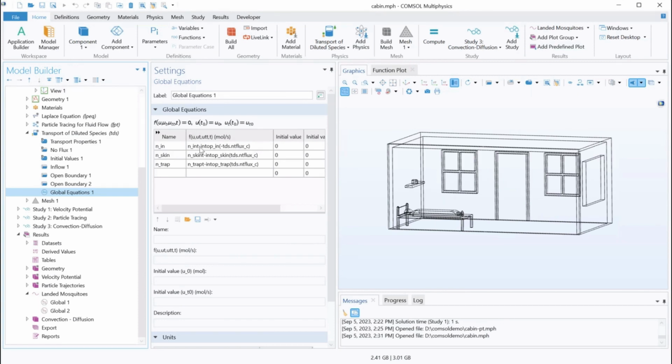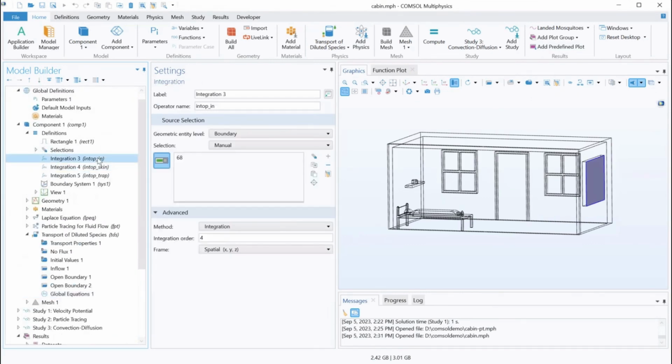So what's happening here is n in t is the time derivative. So this is a built-in expression. This means the time derivative of the expression we're defining. So we're prescribing an expression that we force to 0 that involves the time derivative of our variable. And we're forcing, due to this expression, this time derivative to be equal to the spatial integral of the flux of concentration. So again, this spatial integral here, this defines a boundary. So this defines where it is and says that it's going to integrate over that boundary.